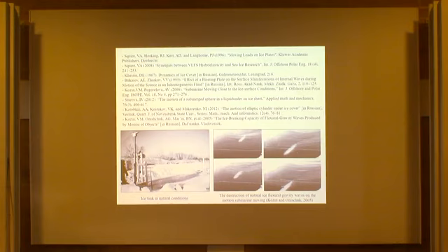Korotkin considers the nonlinear problem of non-stationary waves caused by a submerged elliptic cylinder moving under the ice cover. The possibility of breaking natural ice covered by flexural gravity waves from the motion of model submarine vessels was shown in the work of Kuzin et al. The research on the influence of the thickness of the ice plate, the depth of the body, its dimensions, and the velocity on the amplitude of deflections of the ice plate was carried out on the basis of the theoretical dependence received by Pogorelov et al.